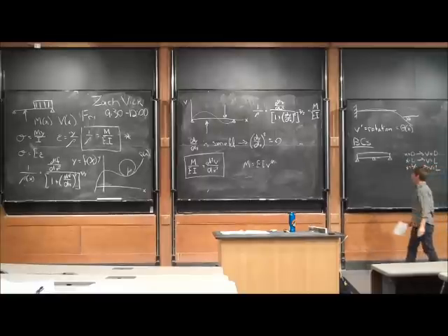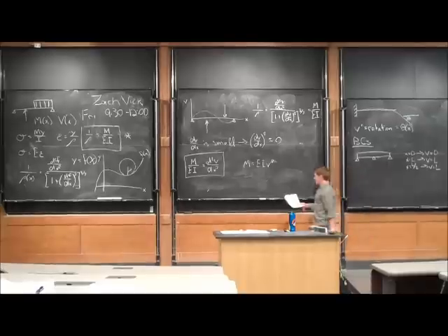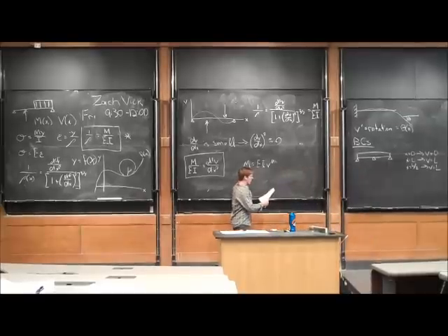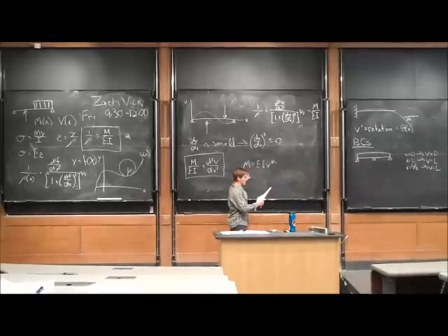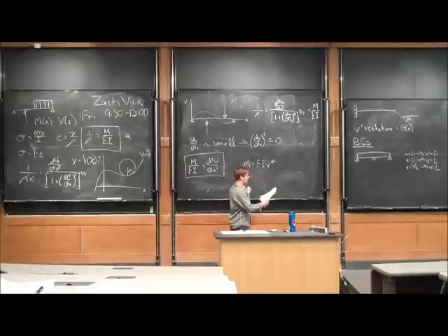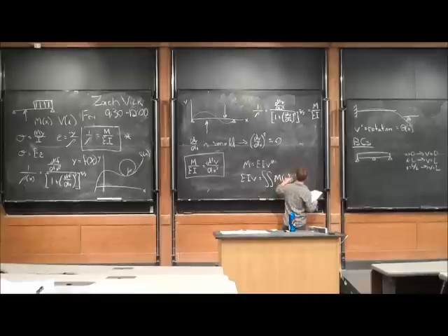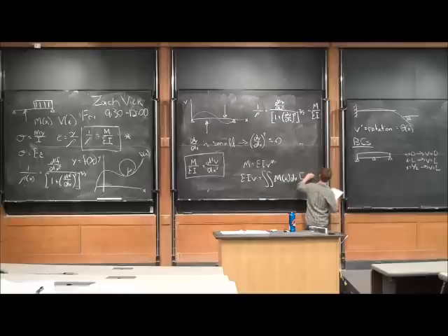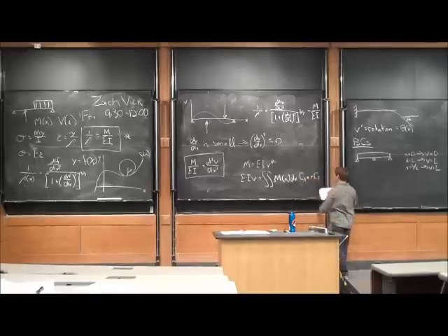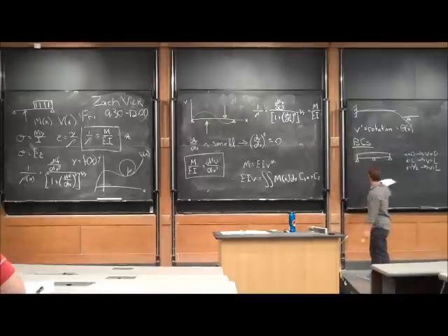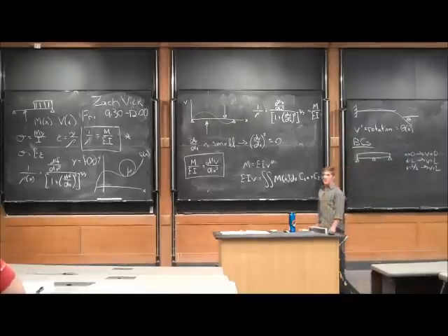So that's an example of a boundary condition, because from this equation, if we're looking for the actual deflection of the beam, we can see that EIv is going to be equal to the double integral of the moment equation that we solved, plus some constant times x, plus another constant. So we need to solve for constants C1 and C2 using boundary conditions.